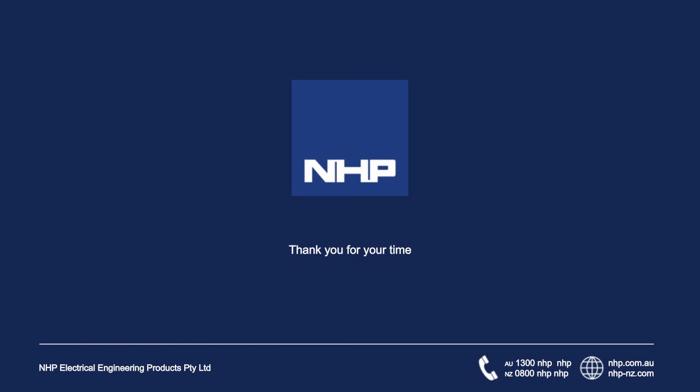I'm not sure I understand what that question is, Daniel, because MCCB type selection, I can only think of that as being a type A or a type B. And surge protection devices, well, circuit breakers are only basically used in front of surge protection devices to protect against short circuits within the surge protection device when they come to end of life. So I'm not sure what that question means.